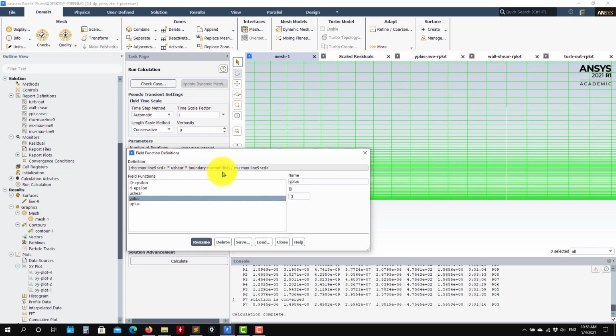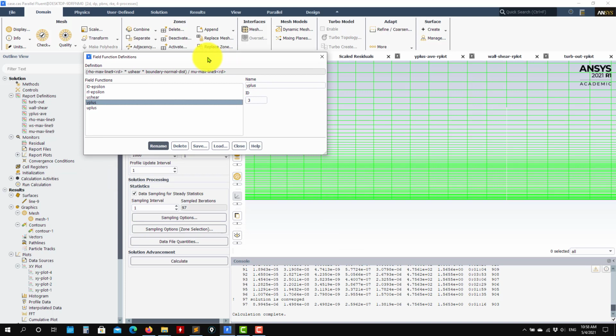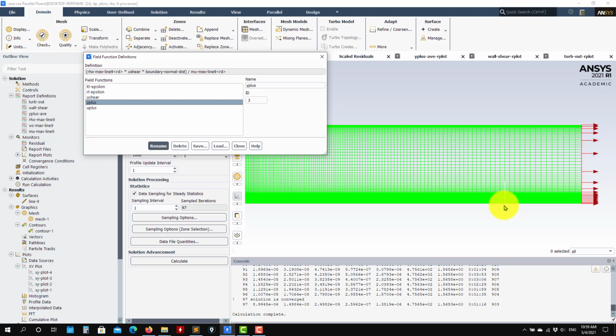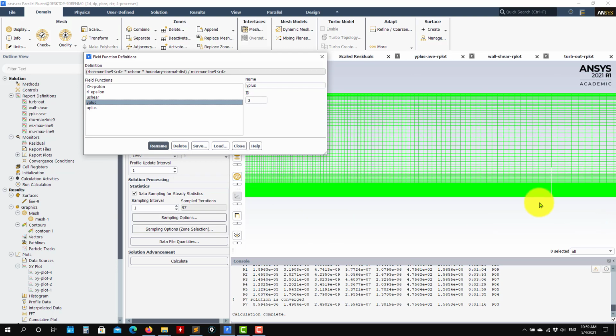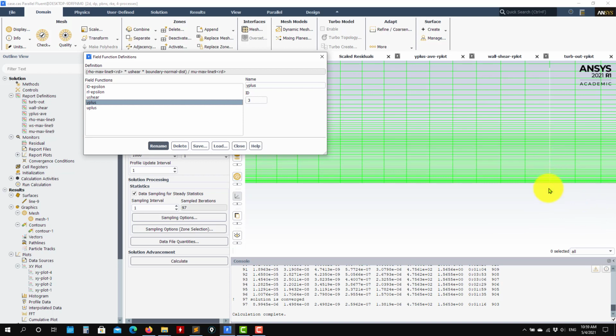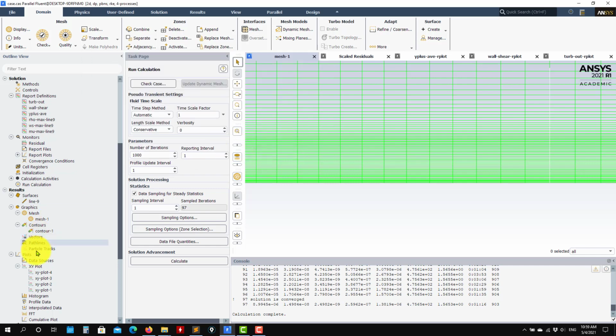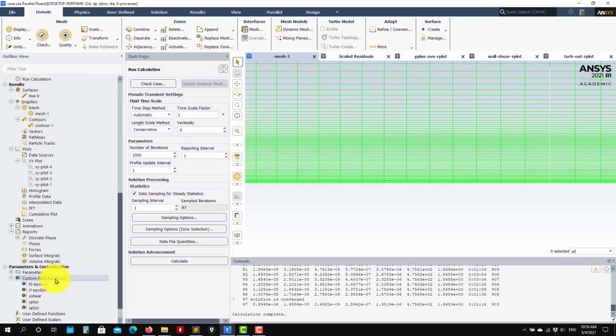Remember that this is computed by default in Fluent, but you don't want to use that one, you want to use your own values. What you need to do is that the point where you start to measure the distance needs to be the coordinate 0. In this case it's not 0, I recall that the 0 is here. So when you get that distance, it will be y minus this one. You translate everything and start from 0 here. But I think it's a good standard practice to use the boundary normal distance. So you compute all those derived fields.